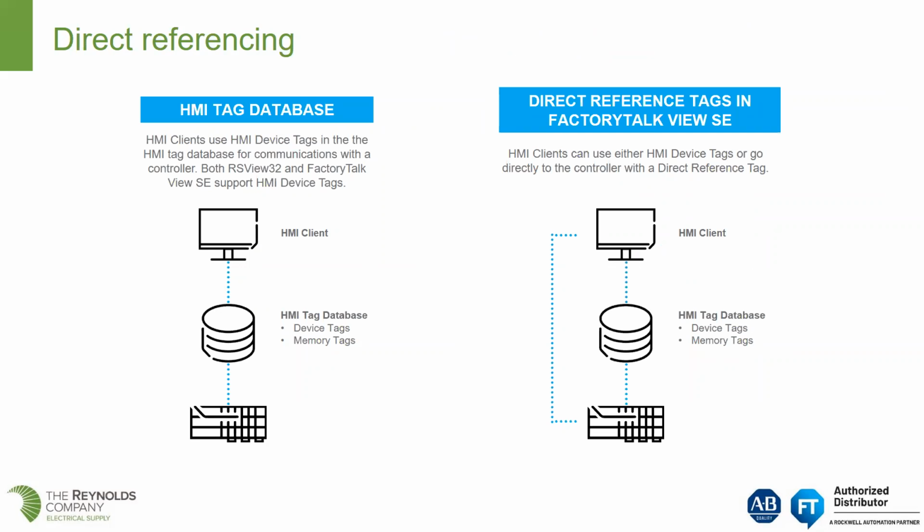RSView32 had an HMI tag database. So we built HMI tags in RSView32, and those tags resided in a database. Today, with FactoryTalk View SE and FactoryTalk View ME, the development software is highly integrated into the Studio 5000 or RSLogix 5000 programming software. And we don't really build the HMI tag database.